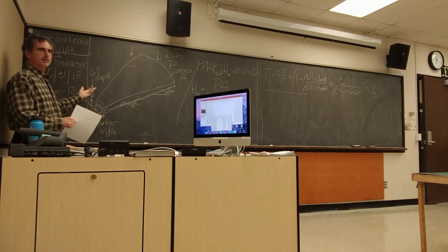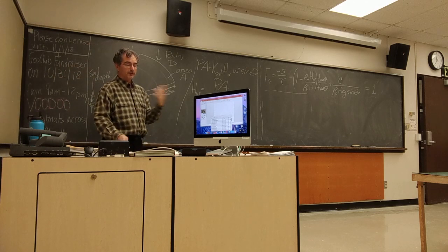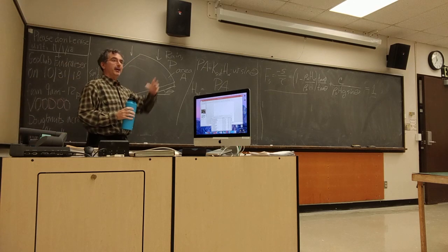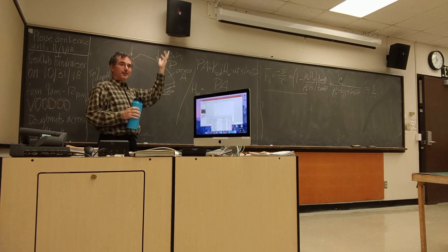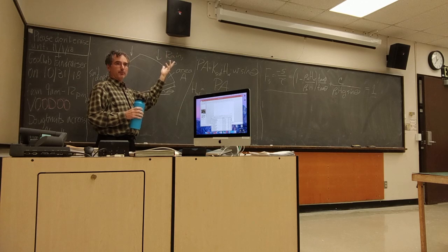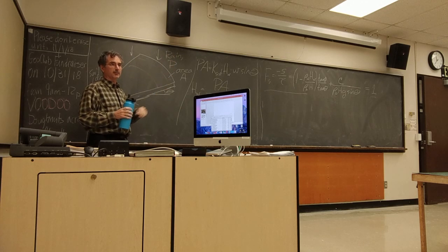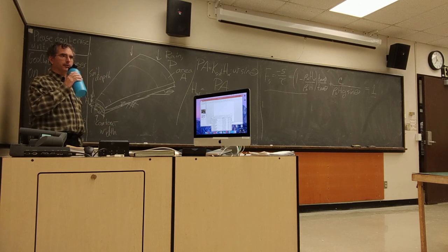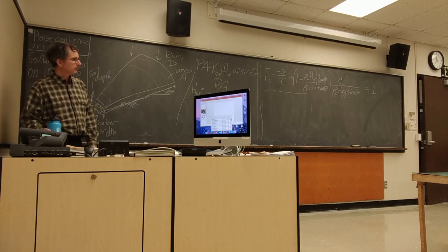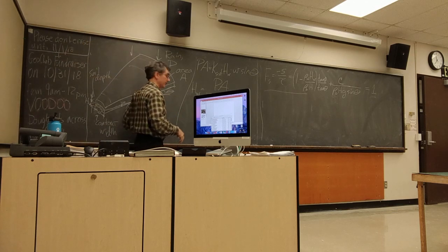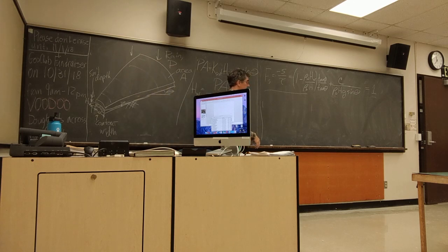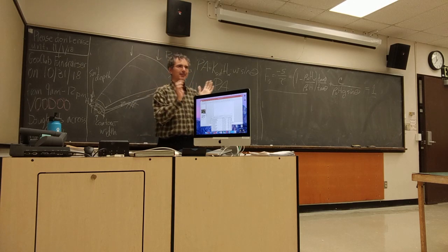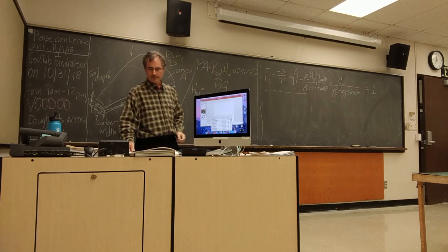What did I say? I said it's raining forever. This is not going to do a good job if we're talking about the pore pressure induced by a pressure wave from a spike in rainfall intensity after it's been raining for a long time, and my soil column is unsaturated technically, but really wet. Pore pressure is 0 through the column. That's exactly the sort of scenario I was sketching for our example of Darcy's law in the vertically draining case. That pressure wave from the spike in rainfall will transmit faster than the water will move. So that's why this can tell us where we need to be a bit more careful.